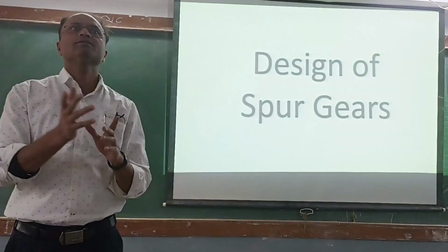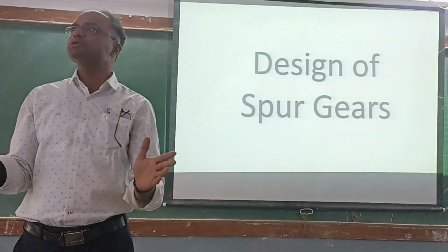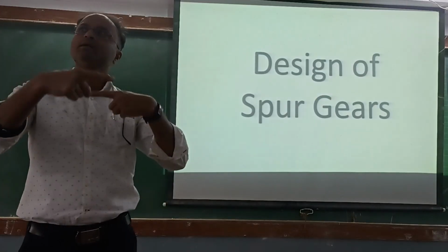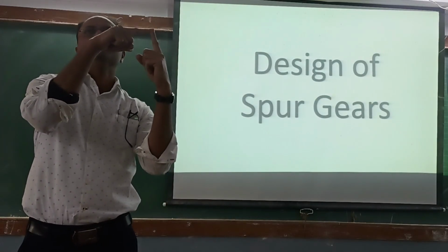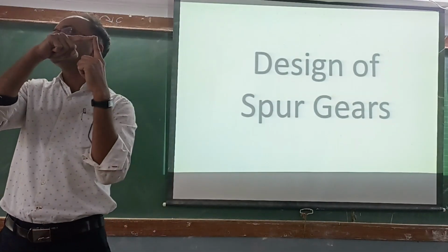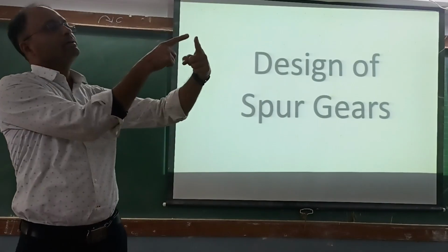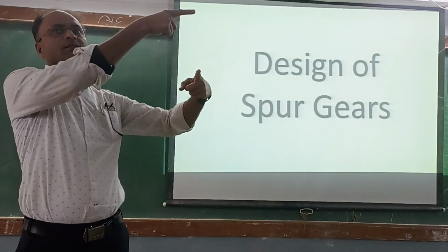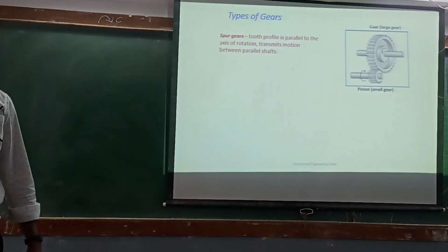What about helical gears? Helical gears are also used whenever shafts are parallel to each other. Bevel gears are used when shafts are perpendicular and intersecting. And worm gears are used when shafts are perpendicular but non-intersecting, like this. Okay, so we'll start with the basics.